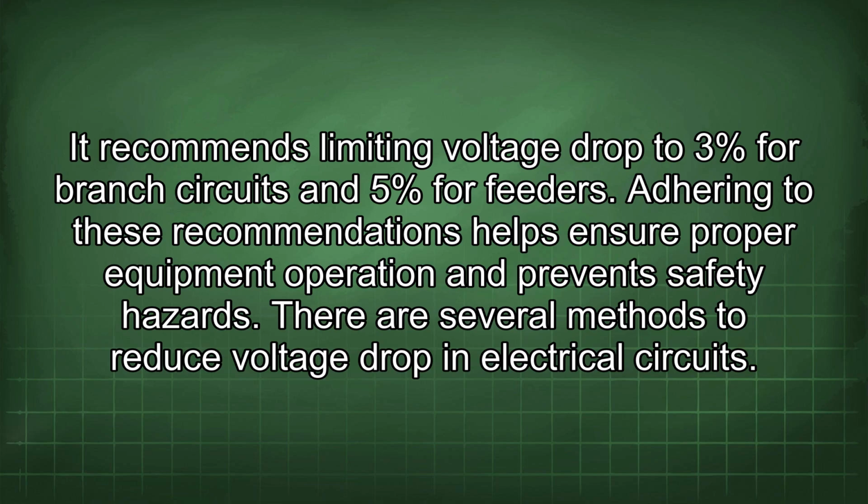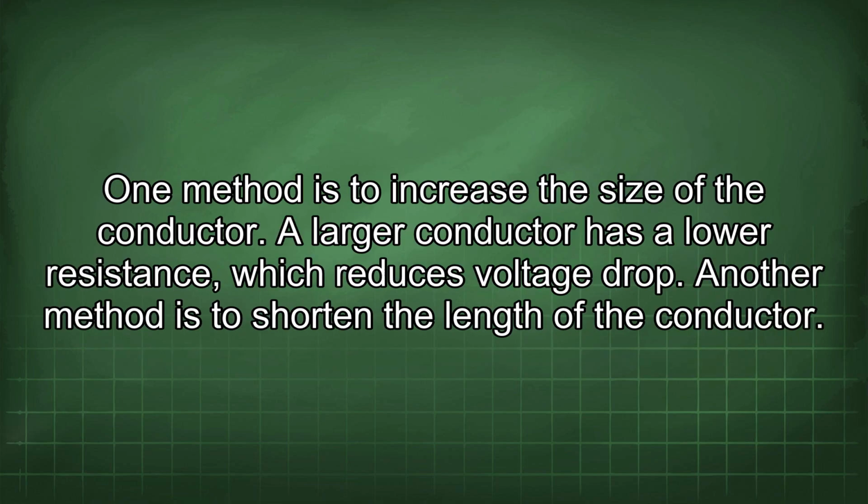Adhering to these recommendations helps ensure proper equipment operation and prevents safety hazards. There are several methods to reduce voltage drop in electrical circuits. One method is to increase the size of the conductor. A larger conductor has a lower resistance, which reduces voltage drop.